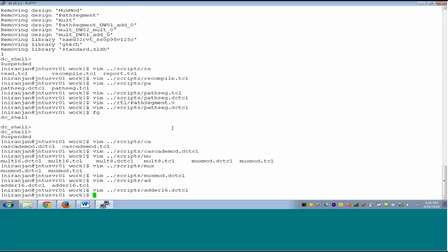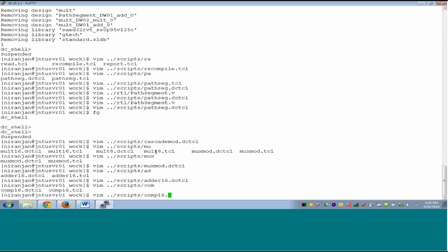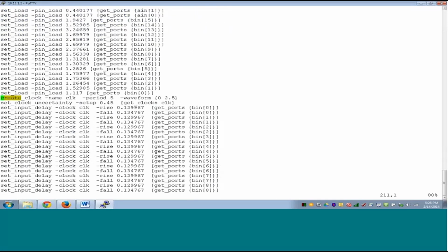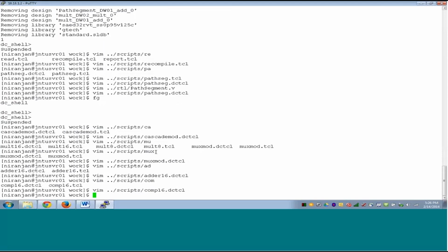It also has a clock. Comparator, I think this doesn't have a... So okay, it also has a... Okay, this is now a virtual clock because there is no port clock. This create clock is not created on any port, so that's okay. So in this case the clock is a virtual clock. So virtually every information that is needed for synthesis is written out by characterize write.